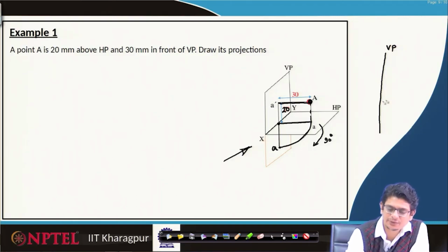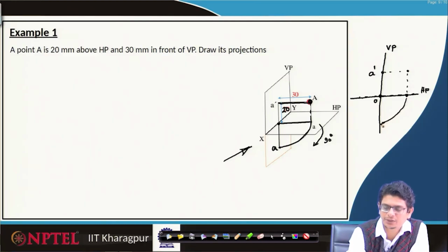Let us consider these x y coordinates, perhaps at this location, passing into that plane. This is the horizontal plane. Point A projection, let us call A prime. Once it is done, from this O to this projection, make an angle of 90 degrees by transferring that radius, so that we can get A.